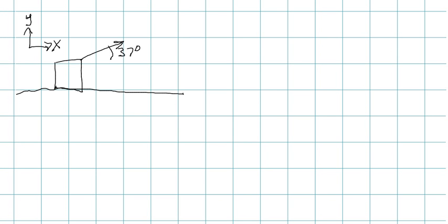What is the total net work? So again, we are having a distance moved of 2 meters. And frictional force is acting on it of 50 newtons. Looks like we're forgetting something here. We are forgetting that our force equals 100 newtons.